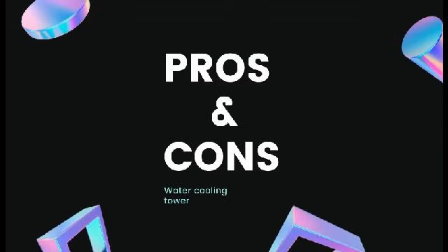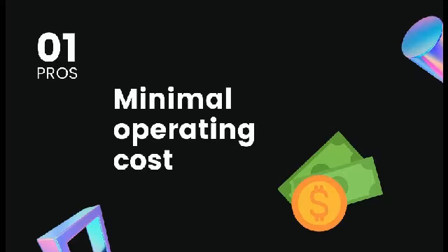Next, let's talk about the pros and cons for the water cooling tower. The first pro is minimal operating costs. We talk about the natural draft water cooling tower, which uses gas naturally flowing into the tower instead of mechanical draft that will cost a lot for the fans.